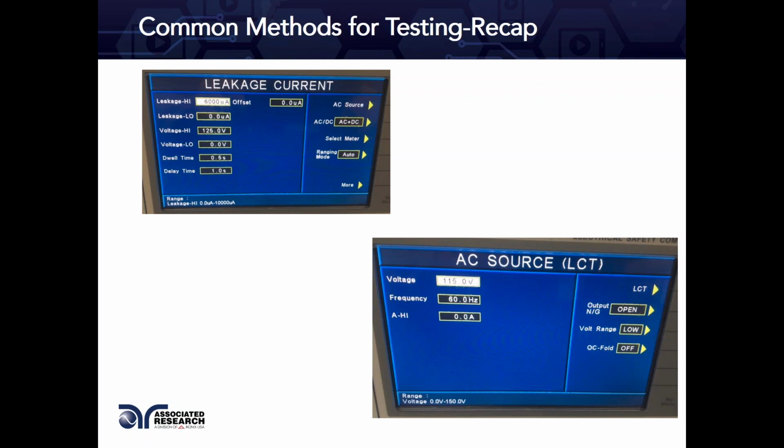under test. Now, if you consider the medical standard for the voltage, it basically tells you to test the device at 110% of the rated voltage. So obviously, you do need a programmable AC source that can be programmed to the specific voltage value that the standard wants you to test at. And so that's the voltage value followed by the frequency. Obviously, you can test it at 60 or 50 depending on the region you're in. And then there's a current high limit that you can always program.